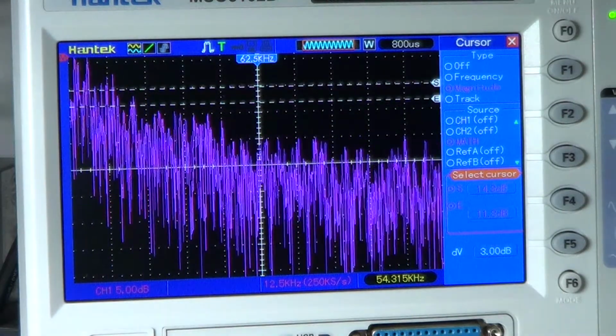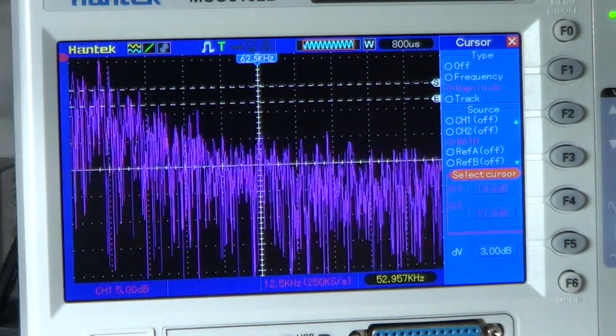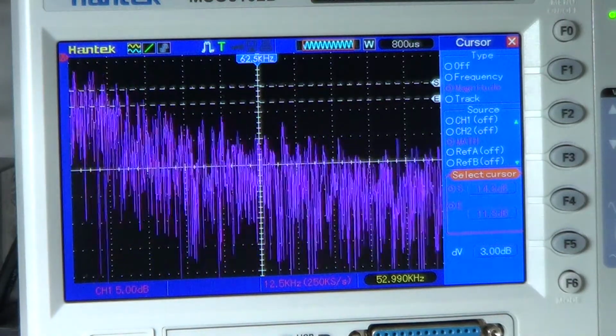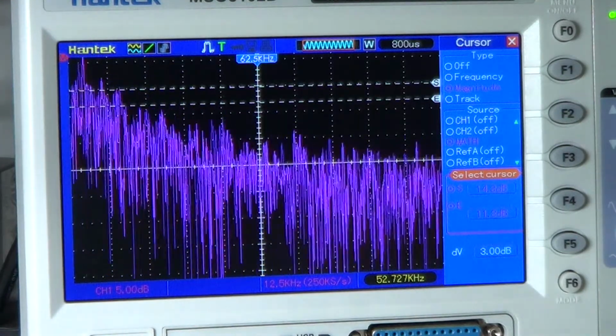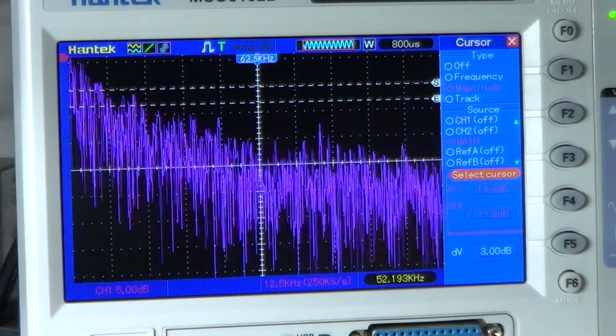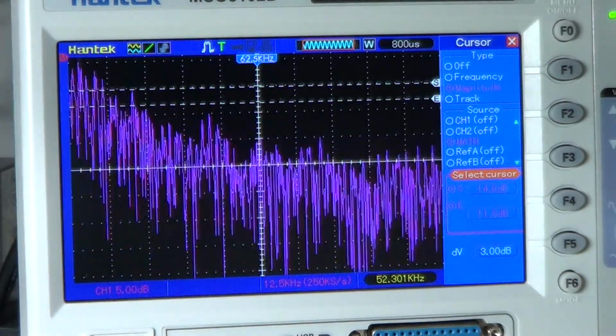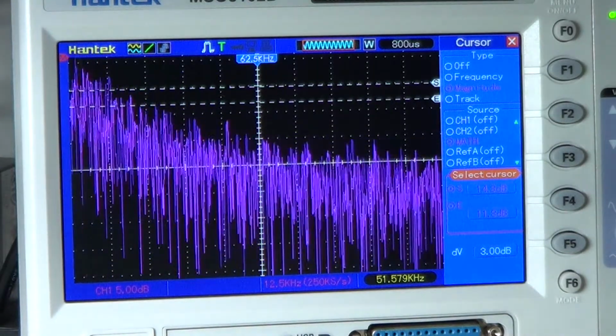Now, when we define how fast the amplitude decreases with the increase of the frequency, we use two reference points in general. Either we go with dBs per octave, where an octave is an interval of frequency where the higher frequency is exactly double the lower frequency, or we can go in dBs per decade. So let's measure it that way.